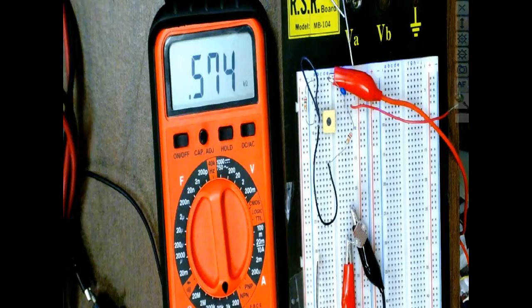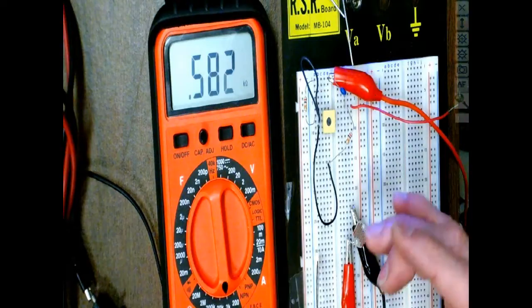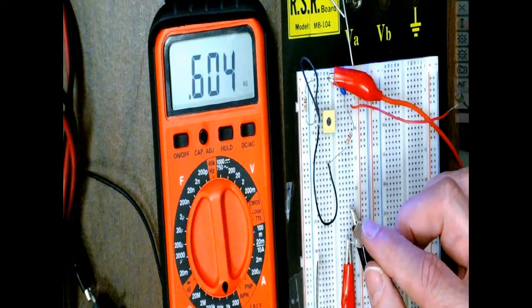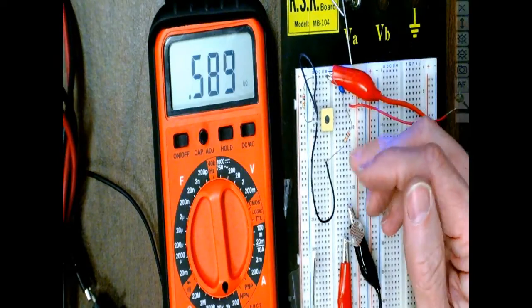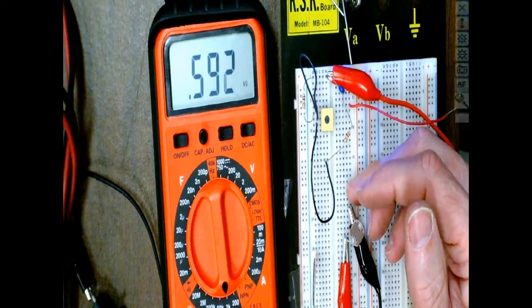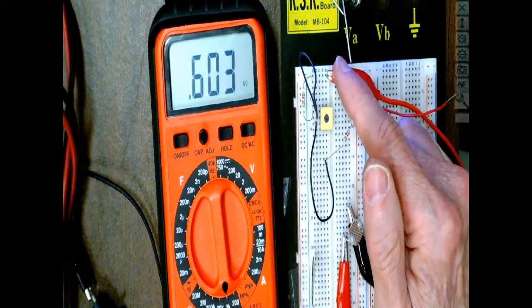We're going to look at a photodiode, but not a phototransistor. These are devices used to sense light, and of course to do different things. So this is a photoresistor. Of course, this varies its resistance with light. To get a voltage out of it, I'd have to put a resistor in series with it, just like we did with the thermistor.